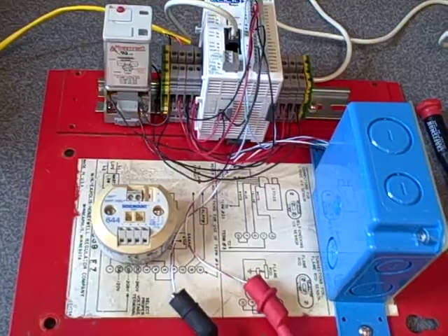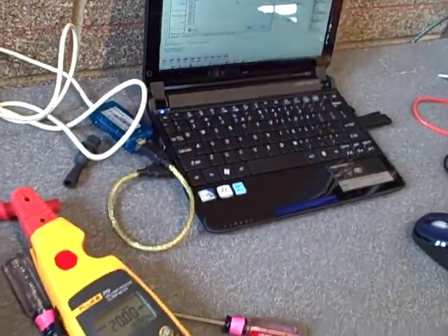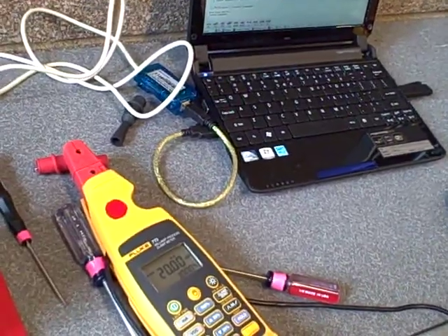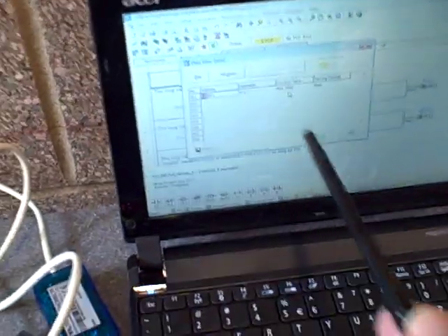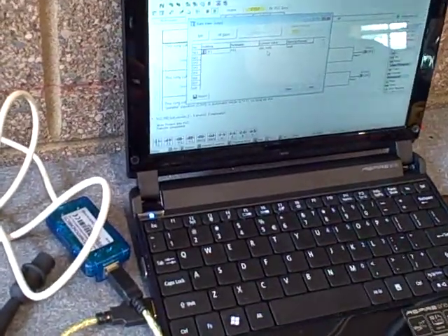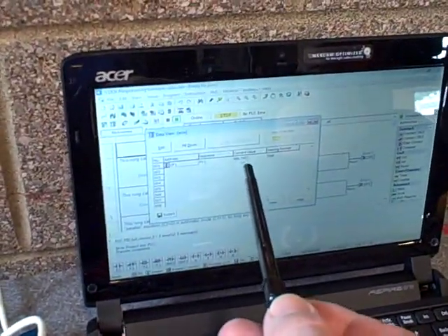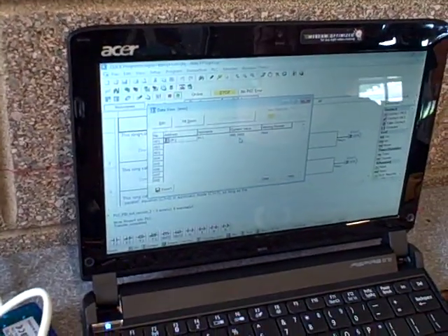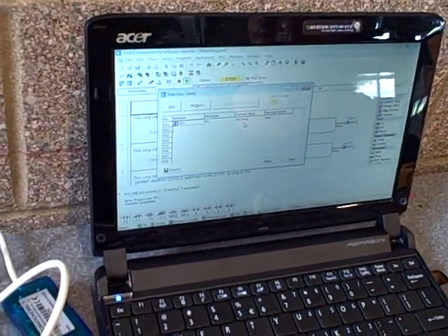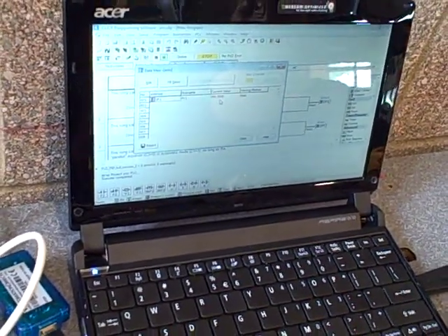So the last thing I want to do is skew the calibration to make it read any lower. If anything, I want it to read a little bit high, that way it's erring on the side of safety. Does that make sense? Since we're already just a tad low here, and we're a tad high on the other data points, I'm going to leave it the way it is. But if anything, I'd be inclined to adjust this up a little bit, not down. But we're within 1/4 of 1 degree, and I have a 500 degree range with a thermocouple. That's better than the thermocouple will do itself, so I'm pretty happy.